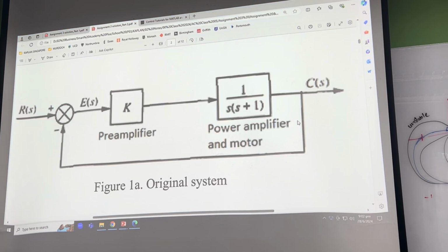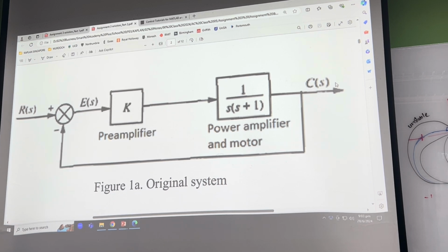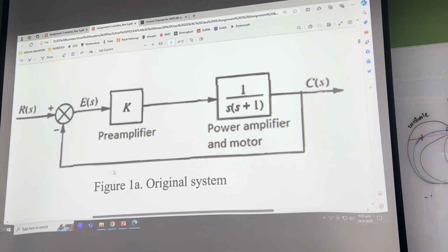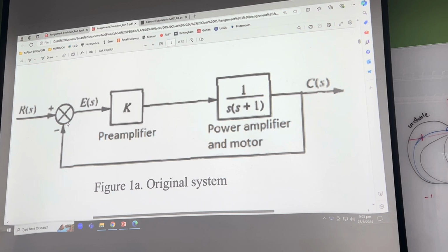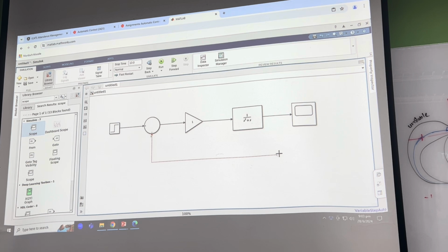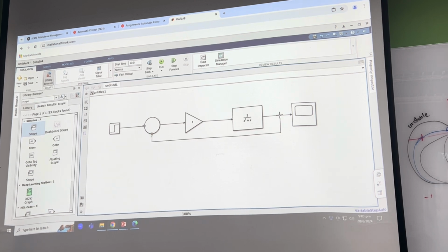So output, at least I have somewhere to see, like a graph. I want to see what it's drawing actually. Then I need to get a take off point to connect to this summing point. If you move your cursor either onto the line, or better on your summing point, then drag the line. Hold the left button, move your mouse until you hover over the horizontal line, and it's automatically connected.